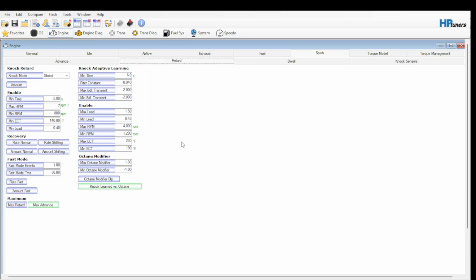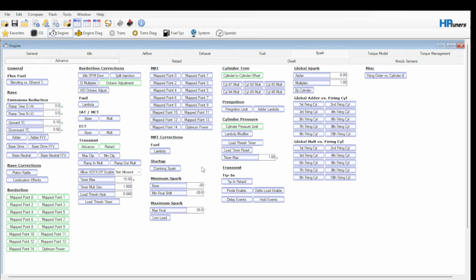And one of the best ways I found you can do that is use the in-truck knock sensor. The truck already has a logic that chases knock, right? The truck already tries to adjust the spark tables to know when it does and doesn't knock, and then it retards a little bit once it experiences a soft knock. Soft knock is still not a great thing, but it's not knock. And you can change these tables themselves, and the truck makes the adjustment itself.